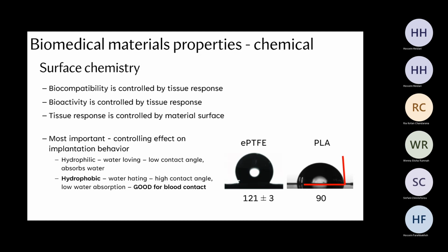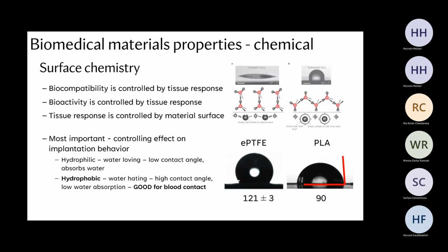An interesting example is the leaves of trees, they actually have a coating that makes them hydrophobic. That's why you see the droplets there on the leaves. And that's not because of the surface chemistry alone, it's because of the topography. If you put it under the microscope, you'll see that it's got this cobblestone shape to it, and the droplets can't wet the surface because the curvature of the droplet is much lower than the curvature of those tiny cobblestones on the surface. So it can be the chemistry of the surface or the topography of the surface.